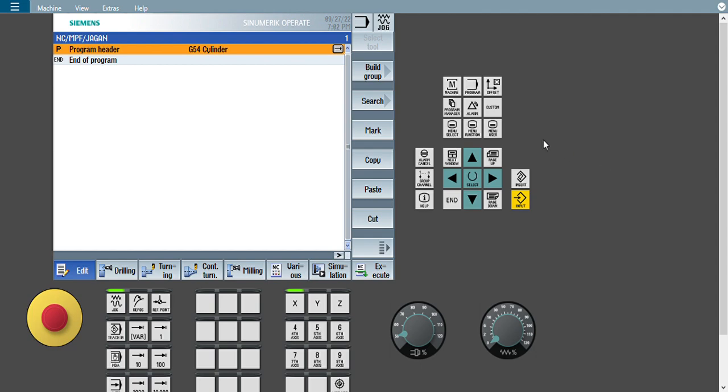And then before going to the cycle, we should take the offset of the grooving tool. We should be clear about which grooving tool we are using, and in which turret location that grooving tool is. Our grooving tool must be perfect as per our cycle and as per the diagram given below.